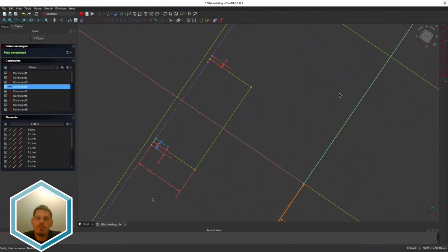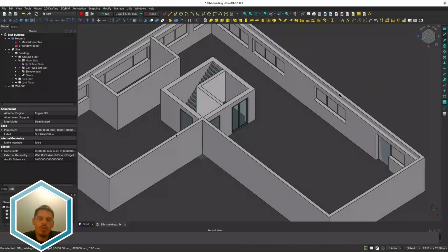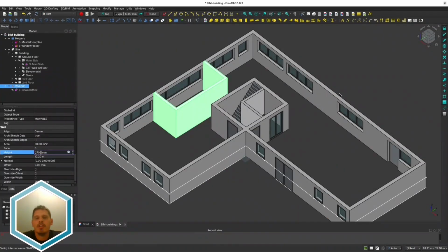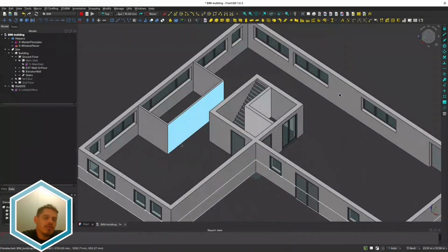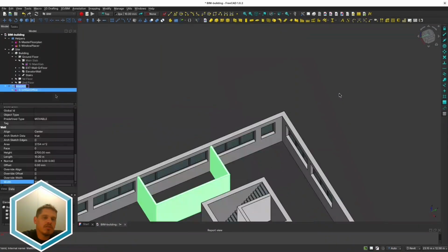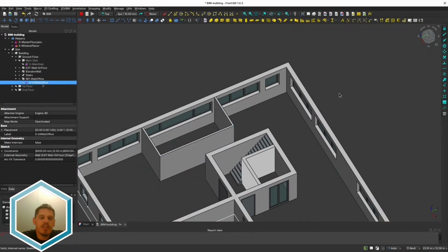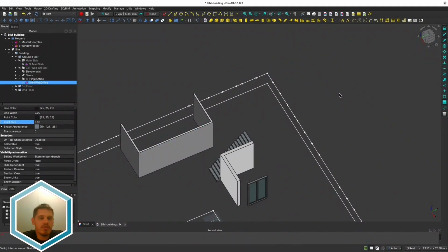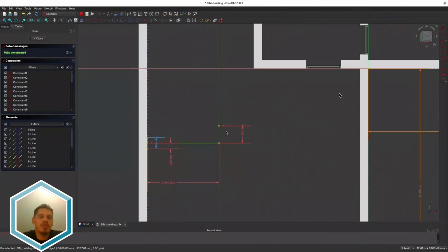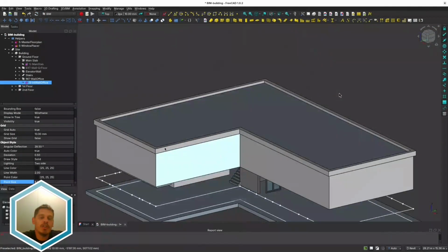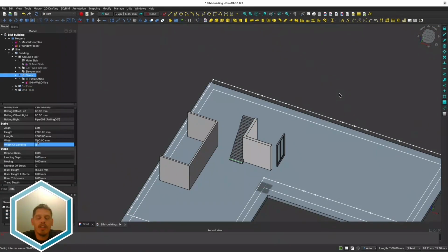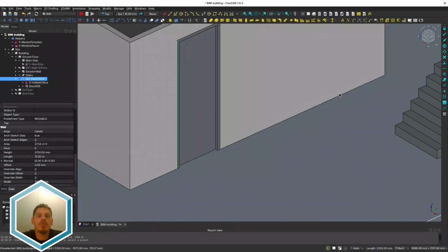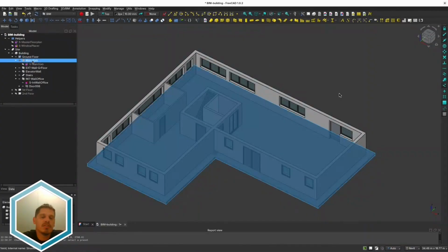And I didn't want to waste too much time adding points again for the door, so instead I use a different snapping setting. And oh yeah, I also forgot to, or I already fixed it here. Part of my sketch, you've got construction lines and regular lines, and the construction lines don't do anything and the regular lines do. So initially for the inside wall I had all the copied lines over, they were still green as well, so I made them all reference lines real quick.